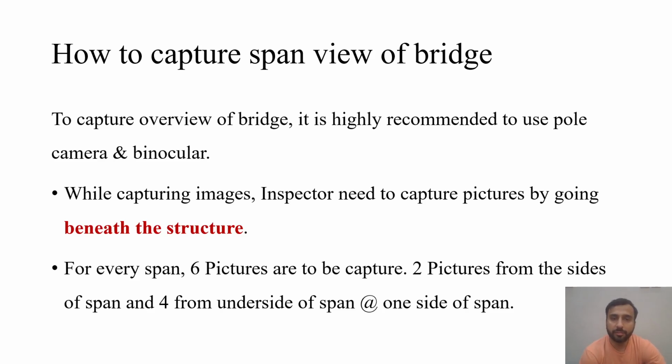So how to capture span views of the bridges? To capture the span overview of the bridge, it is highly recommended to use pole cameras and digital binoculars that are capable of capturing images. While capturing images, the bridge inspector needs to go beneath the structure. If you are unable to go under the bridge, you may use pole cameras that can be positioned in such a way that the camera goes beneath the structure and takes the images.